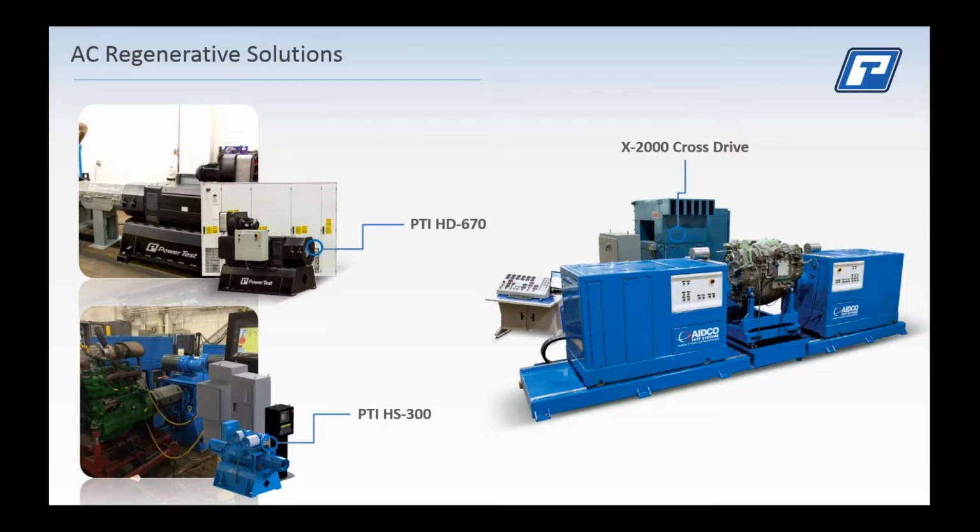In the case of the machine that you see on the right-hand side, we're actually combining some technologies and using a 2,000 horsepower input prime mover, which is an induction motor. And then the outputs, in this case, are actually dual eddy current absorbers to load the power. On the top left example, it's an AC loading only machine for testing engines. So the unit under test would actually be, in this case, a small diesel engine rated up to 500 kilowatts. And the output is an AC induction motor that uses the power electronics to turn that energy absorbed into electricity.